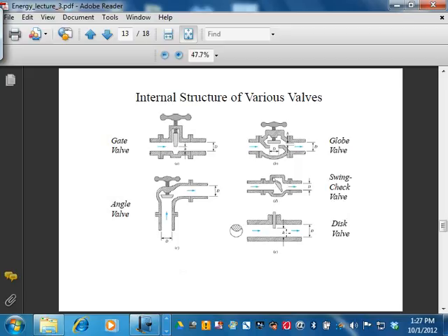It's not quite rare. So the different types of valve, each one, as I said, has a minor loss associated with it. Obviously, this one will be on the high side, and depending on the valve position, the minor loss can change also. If you close it off completely, then the minor loss is infinite.